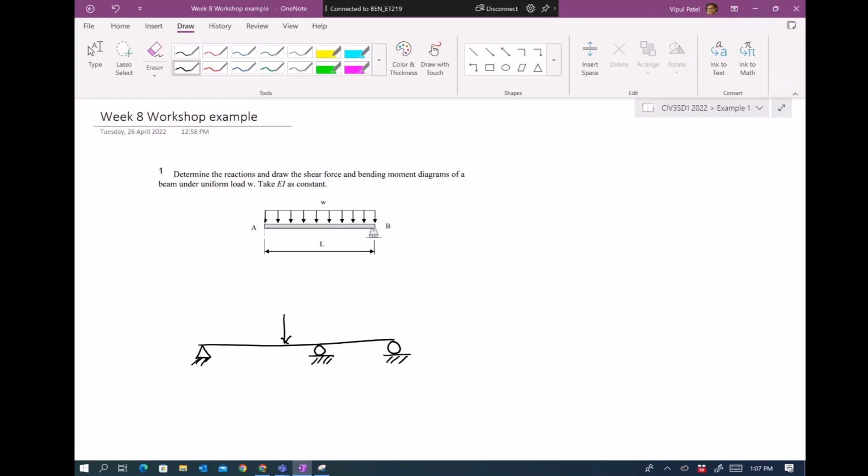So let's say you have this extra roller. Now for that extra roller, what this force method is doing, saying that, OK, that's fine. You remove that extra roller, because for that it will have a deflection like this. Let's remove this extra roller. Then you will have this displacement. With some loading. Do you agree with me?